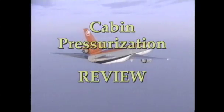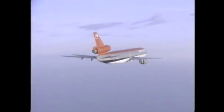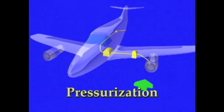In summary, the basic mechanics of pressurization are: ambient air is introduced into a compressor. The air is compressed, it heats up, and is then cooled. The air is then introduced into the cabin, where overflow valves control the air to create a high-pressure environment.